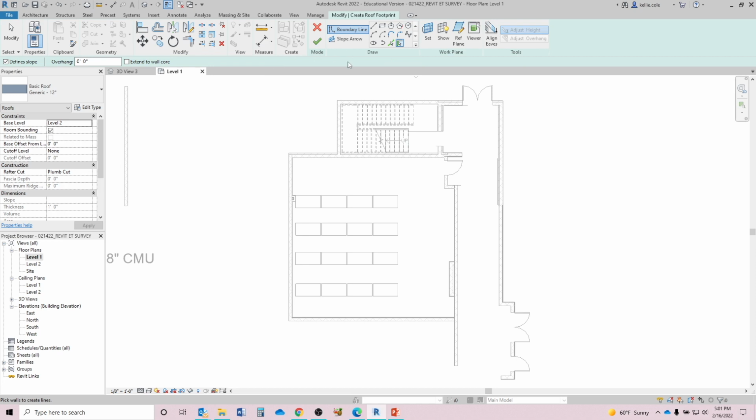I'm going to look just below that area and above the drawing tabs to the area called Overhang. We want our roof to overhang a foot or 18 inches. So what happens if I pick walls at 0 is that it draws the roof right over my wall, and I don't want that. I'm going to Control Z, Control Z. I want an offset overhang of 18 inches. I'm going to type that in and hit enter.